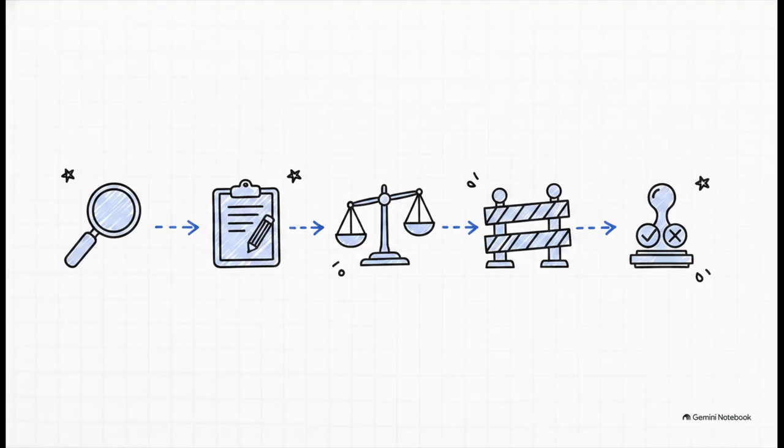So here's the reality check. In the real world, things are occasionally going to go wrong, or they'll just fall short of the standard. In the industry, we call these non-conformances. When they happen, they have to be tightly controlled. You must promptly identify, document, evaluate, segregate, and then disposition these failures. Having a really rock-solid control process for non-conformances is what allows you to accurately report on the quality of your operations and maintain those high standards your clients expect.